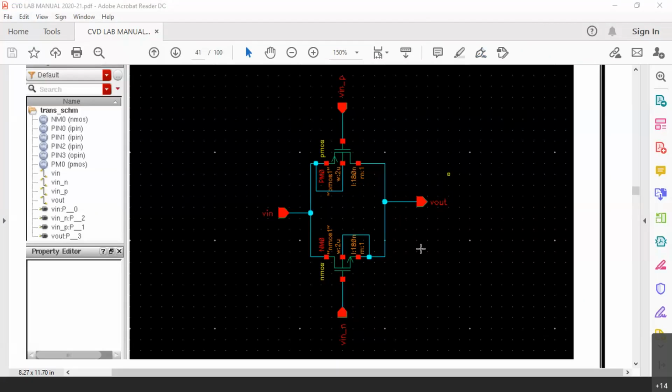When we are able to connect PMOS and NMOS for a regular inverter, NOR gate and NAND gate, we can use the same configuration for obtaining other logic functionalities. Whereas this transmission gate is simply passing whatever is the input to the output. It is not an inverter. For that matter, it is not a buffer either. If at all we want a buffer, let me write a buffer. We should have an inverter and one more inverter.